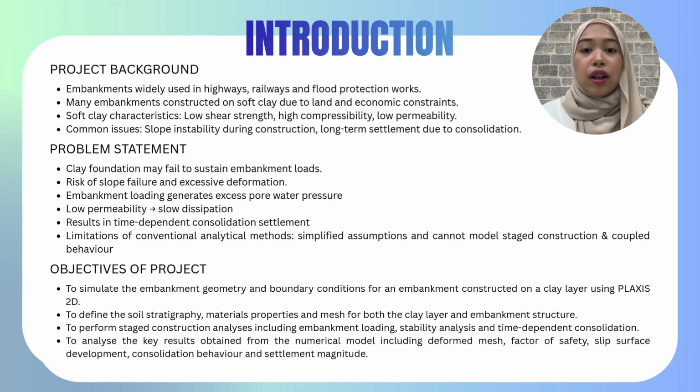The objective of this project is to simulate the embankment's geometry and boundary conditions using Plaxis 2D. Second is to define the soil stratigraphy and material properties. The third is to perform staged construction analysis including stability and consolidation. And the last is to analyze key results such as deformation, factor of safety, slip surface development, and settlement magnitude.